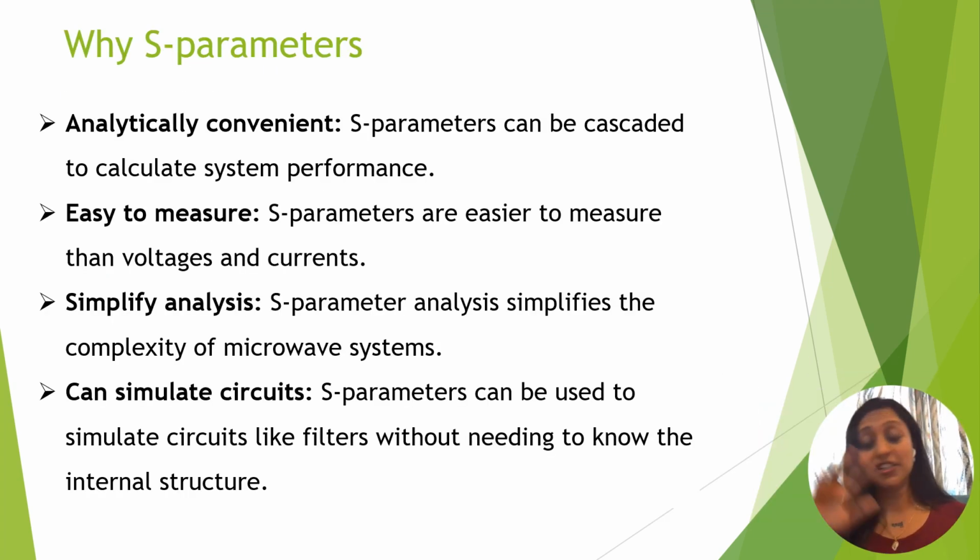Well, we learned so much about S parameters. Now, why am I doing S parameters? I know we have to use S parameters because, as I told you, RF energy is scattering. So why am I using this? The usage of S parameters is analytically very convenient. It can be cascaded to calculate system performance. It's also very easy to measure, compared to any other parameters; otherwise it's difficult to measure voltages and currents.